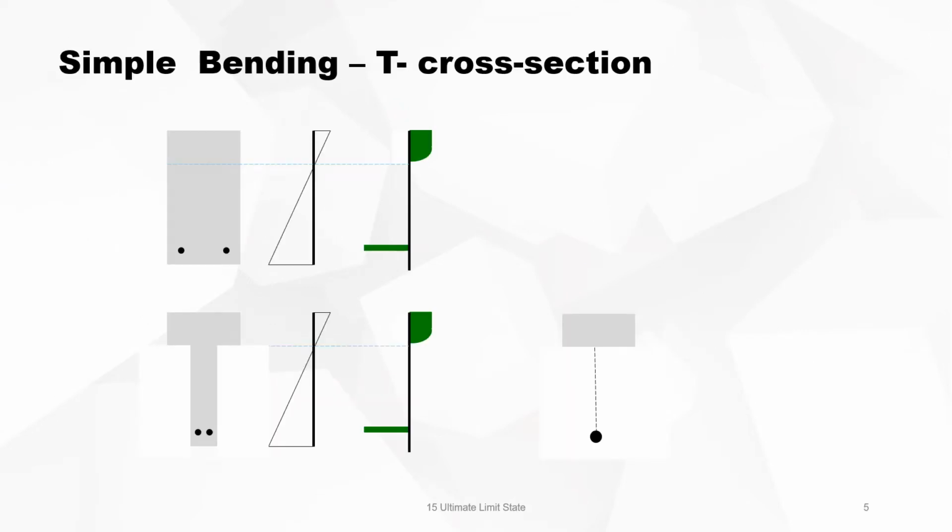Consider a rectangular section in concrete with tension reinforcement, the strain diagram and the stresses. Now, let's say we try to minimize the use of material under the condition that we keep the height of the section and we keep the capacity of the section constant. So what material are we wasting, are we not using? Clearly for concrete, you only use the compressive area and the concrete in tension you neglect. So it's too much material.